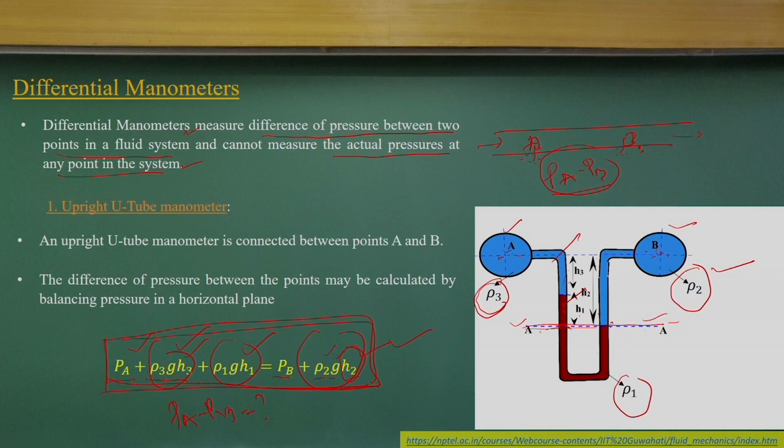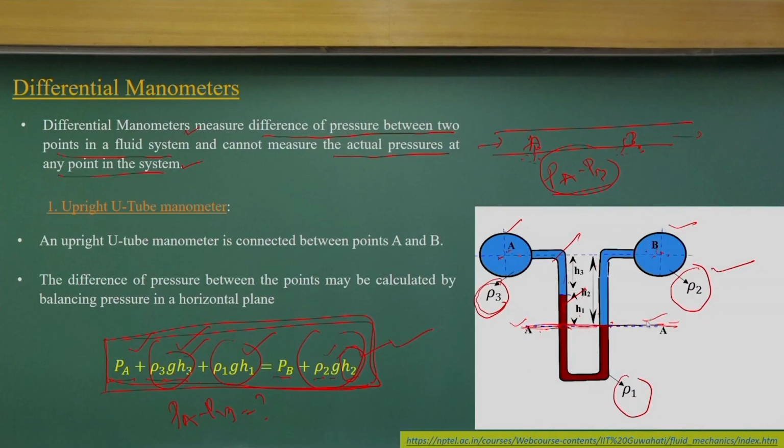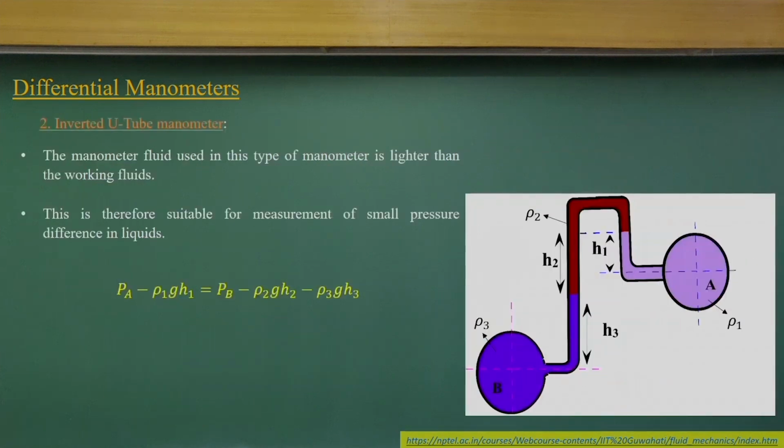So, whenever you get manometric application problems, first you choose the appropriate surface where you can write the pressure equations. If you know that, then you can solve these problems easily. It is not that difficult.